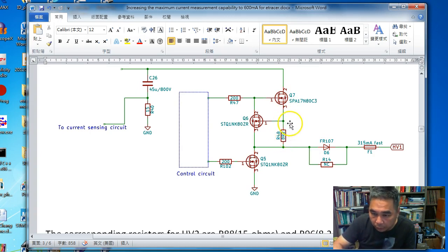When the voltage drop is high, it will turn on Q6, and Q6 will immediately discharge the gate voltage of the switching transistor Q7, turning it off. So we need to halve the value of this resistor so that it will reach the desired voltage at 2x current.